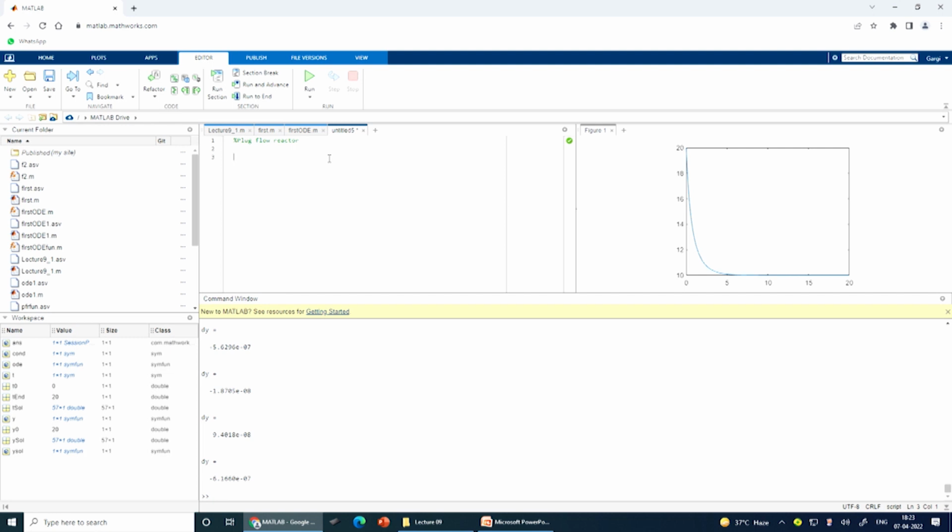And in plug flow reactor, we have a closed system which acts like a batch reactor, but it is a batch reactor in motion, which means basically we have an initial concentration of a contaminant or a compound that we are following. That compound either accumulates or decays within the closed confines of the plug, but the plug flows with time.